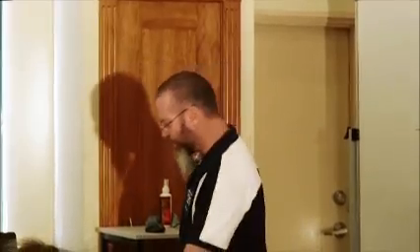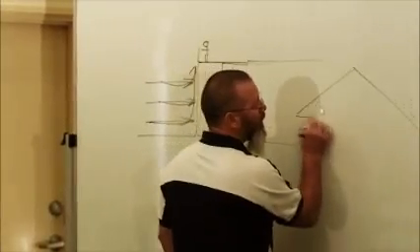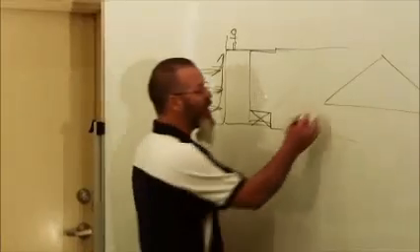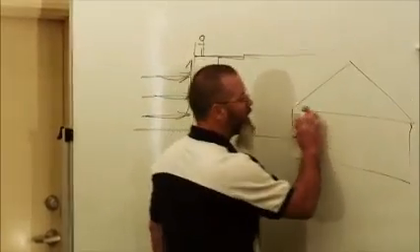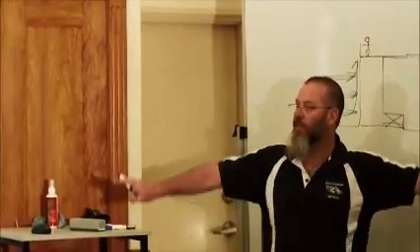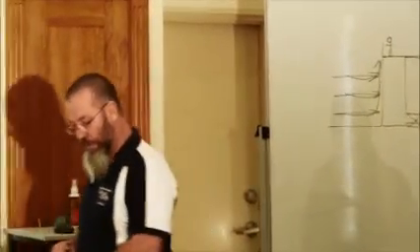A coupled roof is a stick roof, or a truss roof, that's a coupled roof. A non-coupled roof is where you have a supported ridge which is supported either end. So there's nothing in the centre of that to stop that roof from sliding out. That's non-coupled. So if it was a coupled roof or a stick roof, you'd go straight there where it says coupled roof, and all you've got to do is put 2 skew nails in there. 2 3-inch skew nails, that's all you need to hold the roof down.